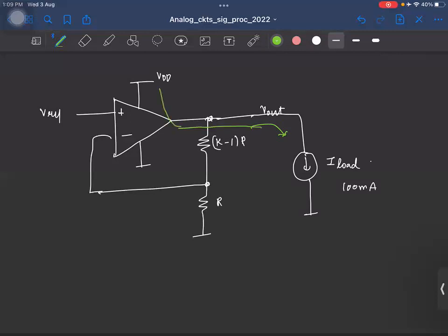to the supply. Okay. So now, as you will be knowing, or some of you might already know, the op amp needs a bias current so that it's operating in the required way you want. Okay. And I call this bias current IB. And this bias current also depends on the current the op amp can deliver. Okay. So let us say if you want to deliver 10 milliamps of current, the op amp can burn say some 10 or 20 milliamps. But let us say you want to deliver 100 milliamps of current, even the bias current that the op amp needs will be proportional to that.